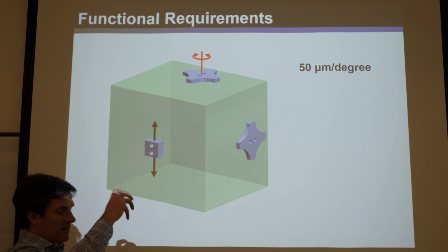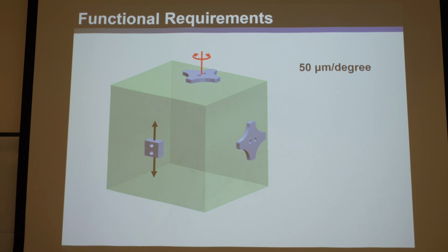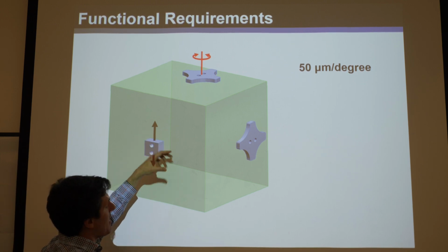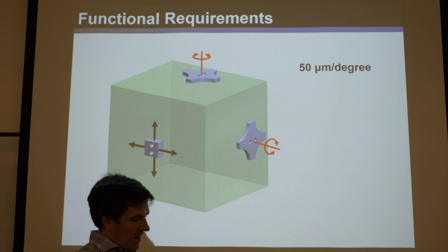you have a high precision stage that you drive with your hand, right? So hands are very not repeatable, as you know. Like what's the most repeatable number of degrees you can rotate? And how repeatable is that? It's not great, right? But if you could make flexures, attach all these within this box, and you could make it so every time I rotated this a degree, this output stage moves 50 microns, say, or whatever you want, to step down, to dramatically increase the resolution and repeatability of your hand, and make it so it moves tiny amounts. And then say you grab this one with your other hand, so you're grabbing it like this, right?